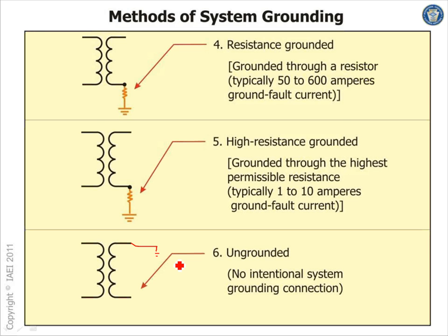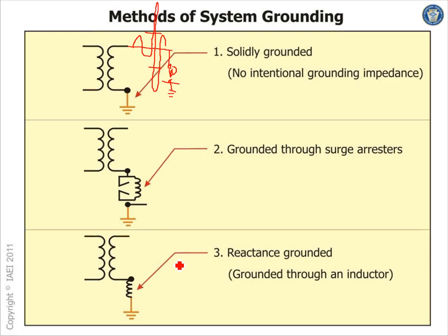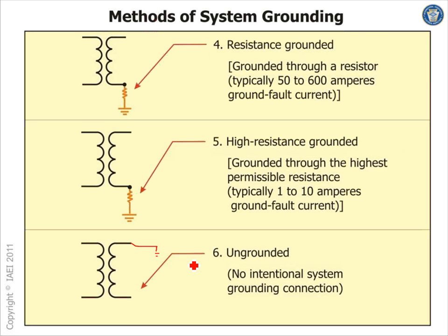So there are two different transients. One is coming from a transmission line getting hit by lightning under normal operating conditions. The surge protective devices, for the most part, will handle it right there. But if you have an ungrounded system like this, and you have a ground fault, as a result of high impedance to the ground, you create a transient in the voltage system here. And that transient could be very harmful. And there are two ways you can capture it. Either you ground the system, one way, but what's wrong with that? You kill the advantage of the ungrounded system.